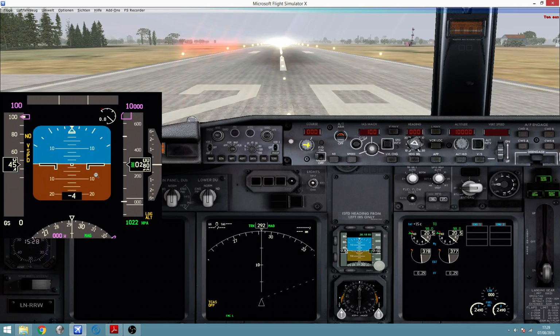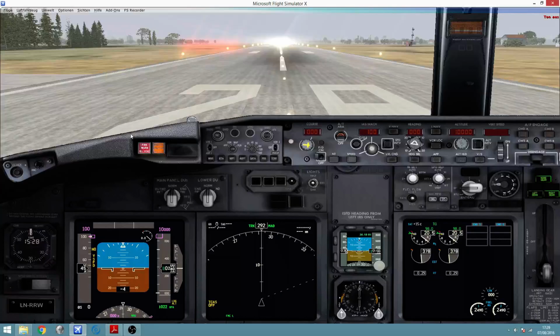After we are established at flight level 100, and when we are starting our descent back to the airport, we will have to again be aware of what's the QNH at Santander, because we'll have to know our altitudes with respect to sea level in the area of Santander, and then we'll have to change again from QNE to QNH at the transition level. And the transition level, remember, that is a function of the QNH.